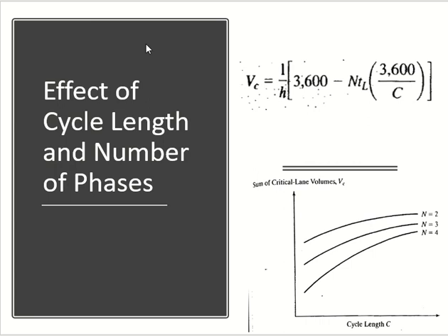Okay, so you see the problem now. I have an intersection and the signal only has two phases, so where will the other people go? Okay, clear? So two phases has a movement problem. It has lot of restrictions. I cannot just apply it wherever I want. I will show you the case, no problem. With two phases. Okay, so but you see the problem. If I keep on giving two phases everywhere because I'm getting maximum VC, it will create a problem for me. It's not possible every time.